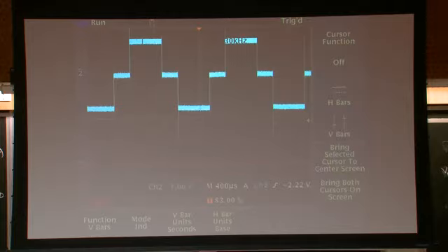As we saw in class, it uses 3 levels, 0, positive, negative, to create something that somehow resembles a sinusoid. And as you can see, it has half-wave symmetry, so we do not have any a_2k, b_2k, or even harmonics. So we only have to worry about the odd harmonics.